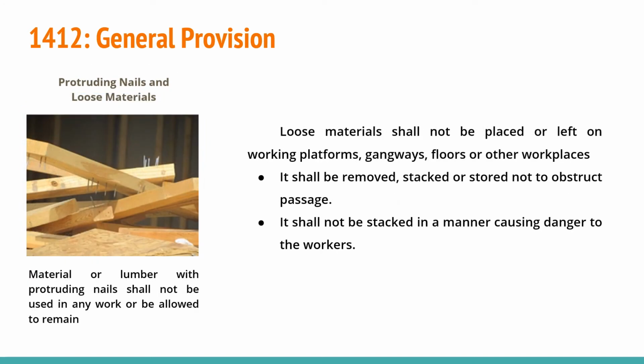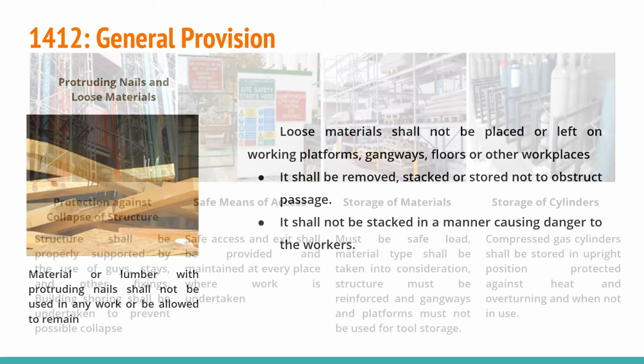Protruding nails and loose materials. Under no circumstances will materials with protruding nails be allowed to remain in the area. It's quite hazardous to the workers. Loose materials are to be removed and stacked properly to avoid obstruction. They should not be stored in such a way that they are hazardous to the worker.